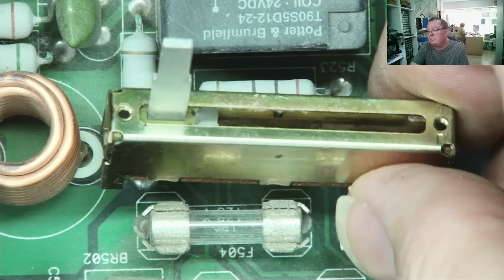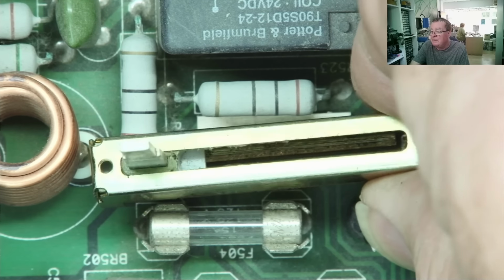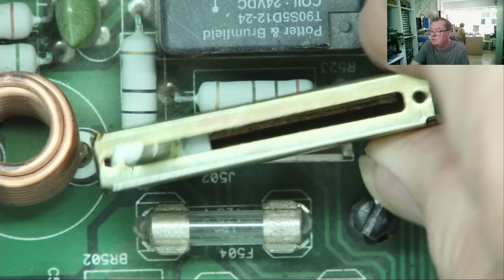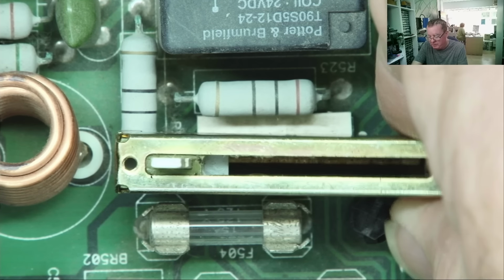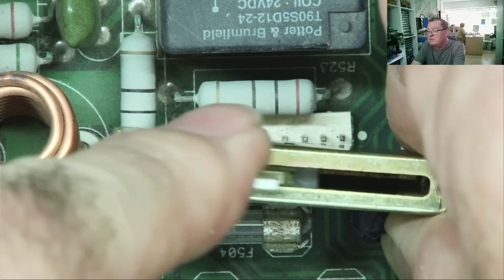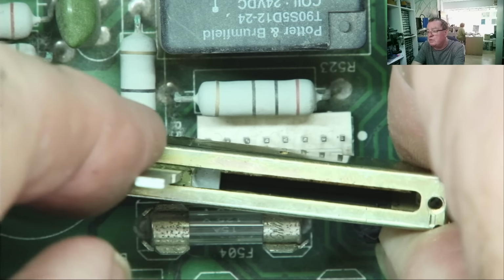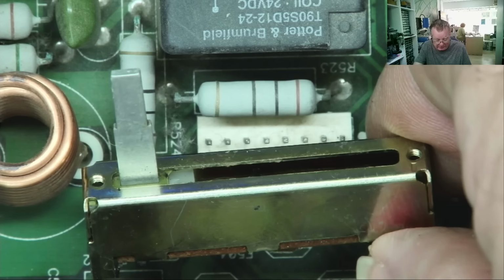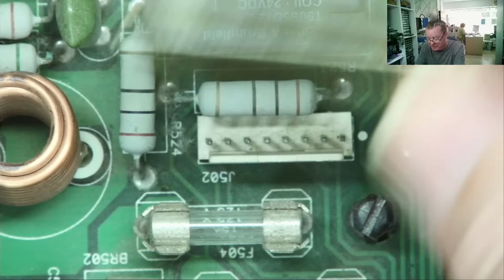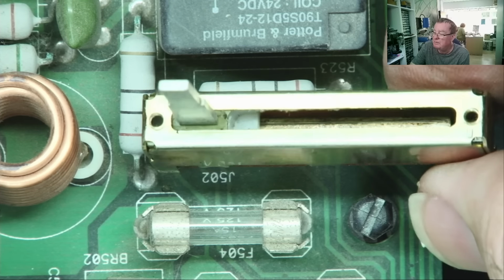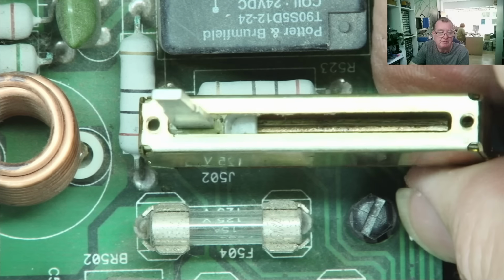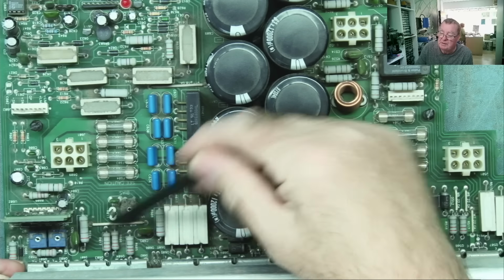These ones in particular in audio mixers, because of the design, which effectively is open, it's very easy to get dust inside there, and the dust acts like sandpaper when you move the slider. So not only is the dust effectively making the connection worse, it's also wearing away the carbon track, and after a short time they'll fail. So these are very common failures, along with the trimmer pots. You can try switch cleaner in these, but most likely your best bet is just to replace them. And the same goes with this type.